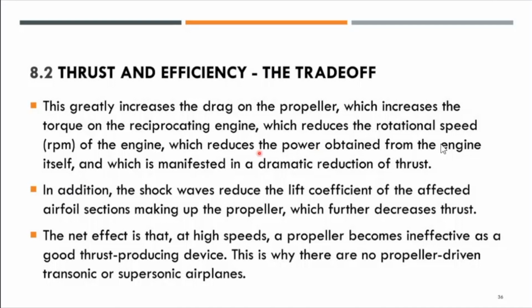So instead of getting more thrust, you will get less thrust. In addition, the shock wave reduces the lift coefficient of the affected airfoil sections making up the propeller, which further decreases the thrust. There is a limit to the rotation of the propeller.